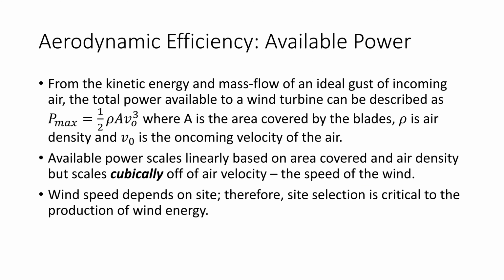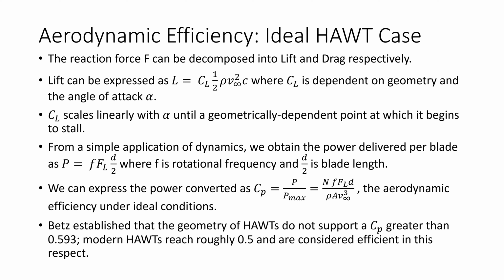That reaction force F, shown on the previous slide, can be decomposed into lift and drag. Our lift is driving the system. We have it characterized there. And from that and some applied dynamics to a uniform rotation, we can figure out the power and then relate that to our previous available power as a coefficient of power, the converted power, which is our aerodynamic efficiency under ideal conditions.